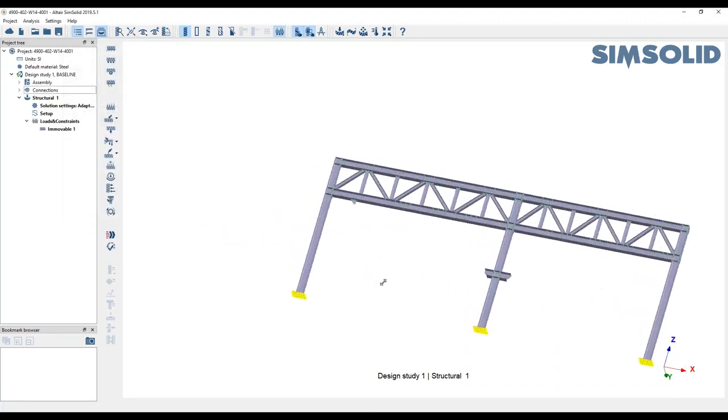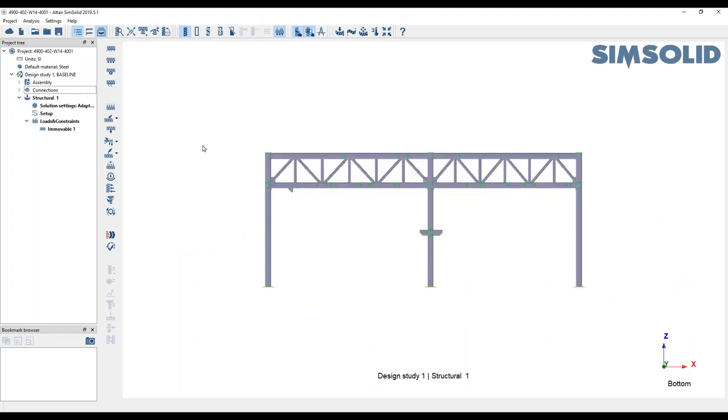And we're simply going to apply a simplistic load. It's a gravity load, and we'll get stress due to its own weight of the frame. And the gravity is defined by a vector automatically, so that's going to be in the -z direction. Okay, and I think we can check if everything's okay. Now that's checking for any rigid body motions, and that's a pretty good check to check if any of the constraints or contacts are missing. Now, because it's a pretty big model, it'll probably take, I hope, not too long.